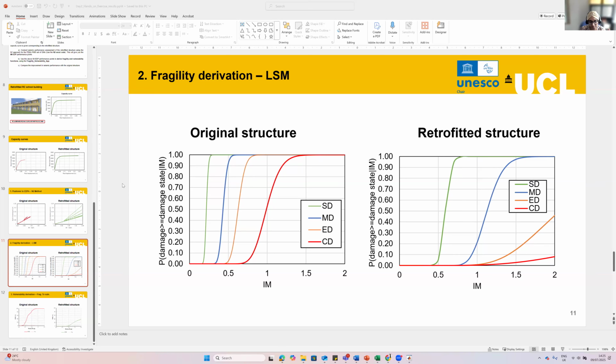Again, this is another very big topic, and you can use any of the ground motion repositories, provide the sorting parameters or criteria for selection, and then select your set of ground motions. We have used scaling with 20 scaling parameters, so each ground motion is scaled 20 times so that we get enough data points for regression. So thank you.